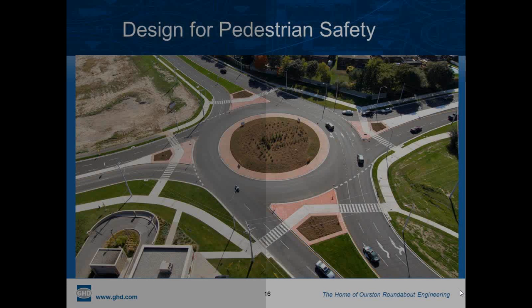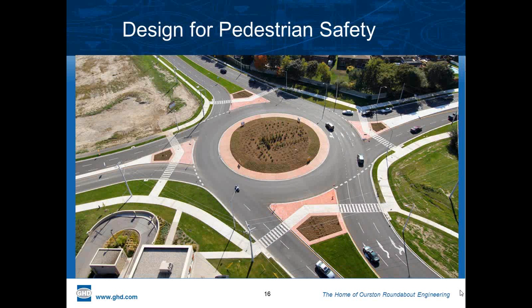Well, what we're seeing coming out of the U.S. Access Board is the regulation or requirement. If it goes into law, then all two-lane roundabouts will require some form of red indication or traffic signal accommodation. Recent discussions between Federal Highways and Access Board representatives seem to be closing the gap on the interpretation of what accessibility means. Does it require a red indication?